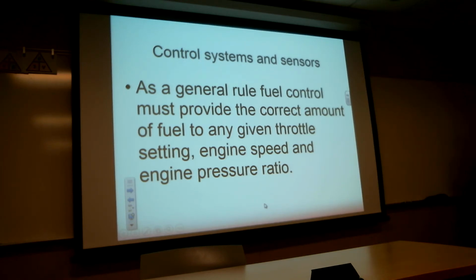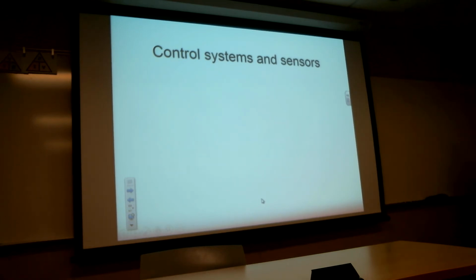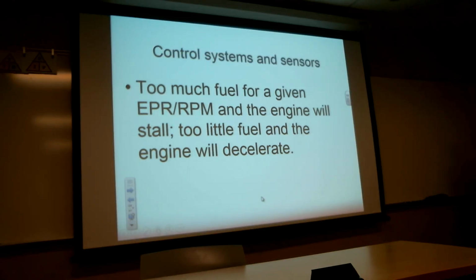So they put chairs inside the airplane, fly people one direction, they'll fly cargo back the other direction. Pretty simple little procedure. Takes like 20 minutes to do it, and you can change the thrust rating. In the case of the engines I was working on, from 68,000 pounds, you can push them all the way to 78,000 pounds in about 20 minutes. Pretty easy, but what you're doing is changing the basic setting of the FADEC. Did a bunch of those for Delta companies.